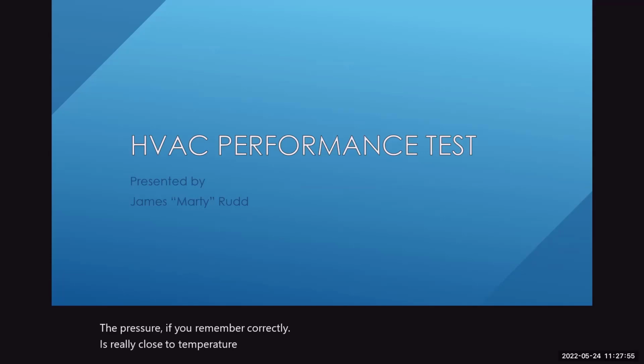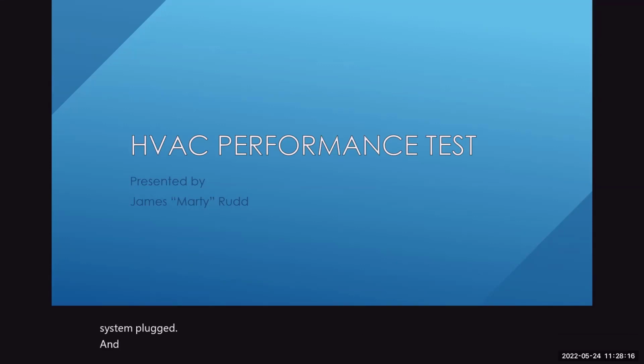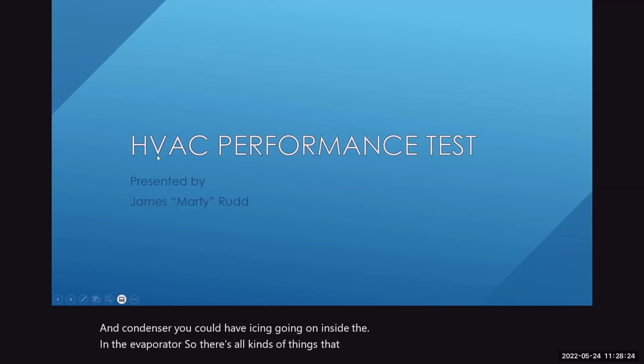So you can actually use these pressures to diagnose a possible fault, either the compressor not working correctly, you could have a plugged AC system, a plugged condenser, you could have icing going on inside the evaporator. So there's all kinds of things it can do. So let's go ahead and get started.